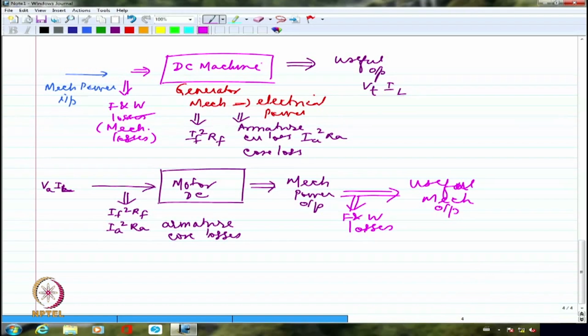Generally in a DC machine, we are not going to laminate the field and we are always going to give a DC current to excite the field. So what I am giving here is also a DC voltage. This is a DC voltage and this is a DC current. Because it is all DC completely, there is no hysteresis, there is no eddy current. Eddy current and hysteresis will show up only if I am going back and forth in terms of the flux, or if I am traversing the hysteresis loop, which never happens in a DC machine's field system.